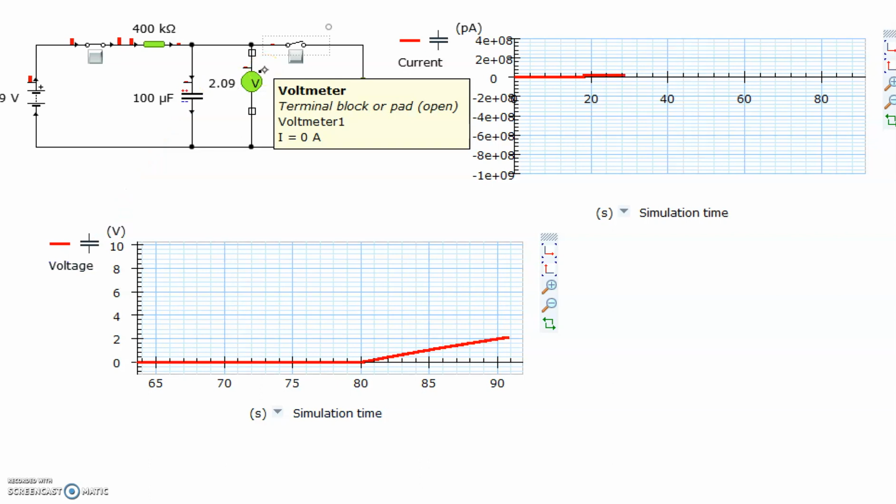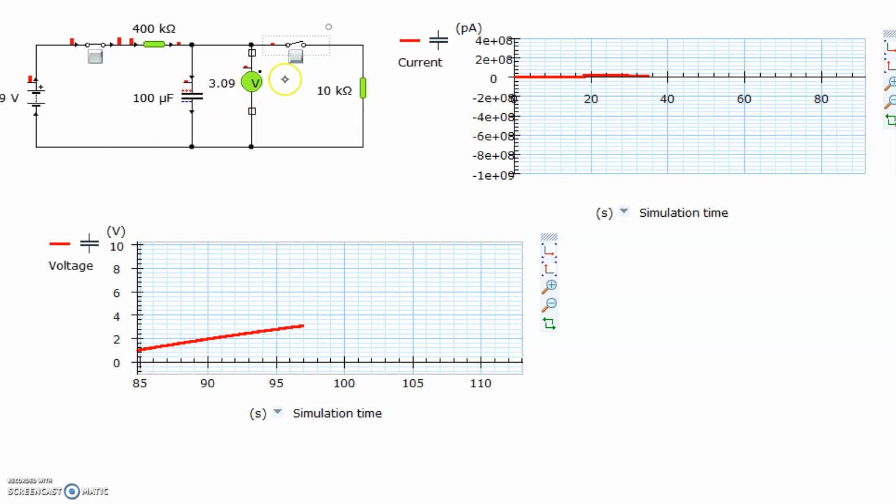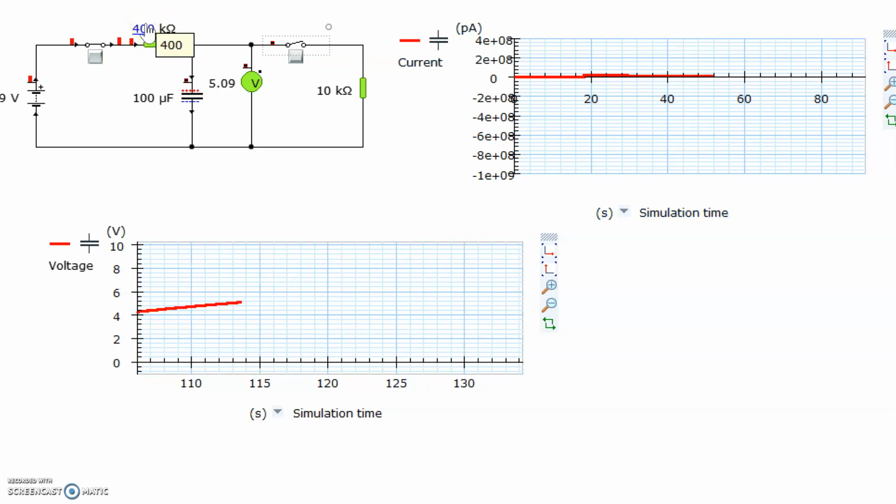So what you can do with this, you see, is through some electronic components like a 555 timer that will turn something on when it gets to 2/3 the supply voltage. So the supply is 9 volts, so let's just say when that gets to 6 volts, then that could be used to activate something. And we could change that 400 kiloohm resistor with a potentiometer, so we could make it variable. And you can see not much current at all.